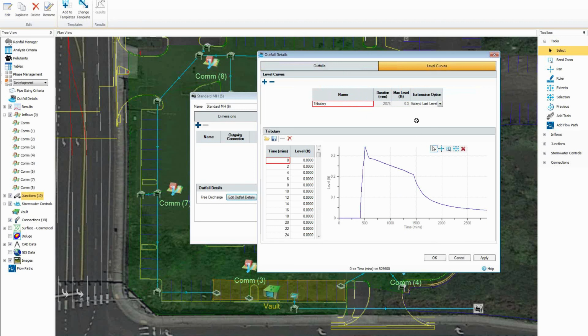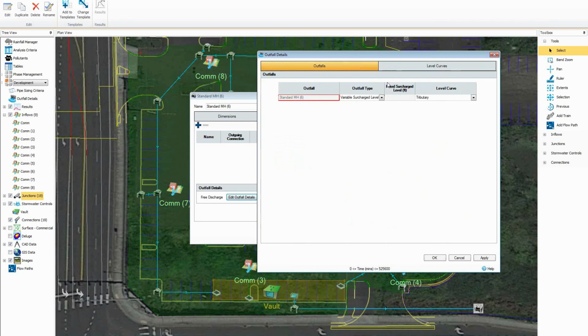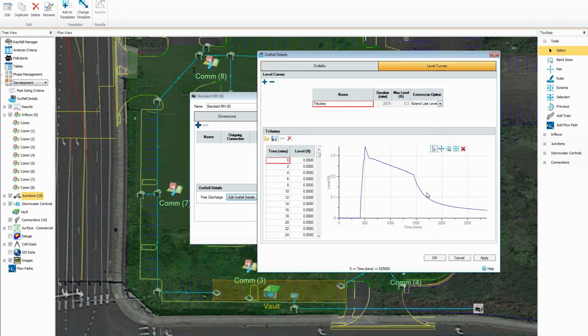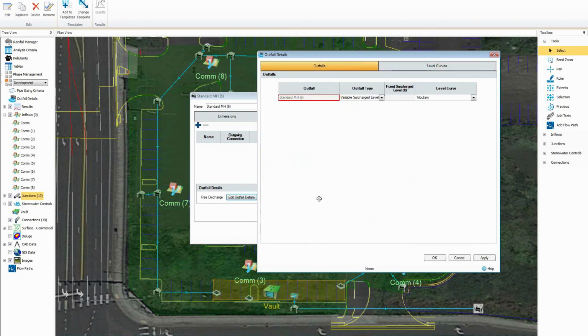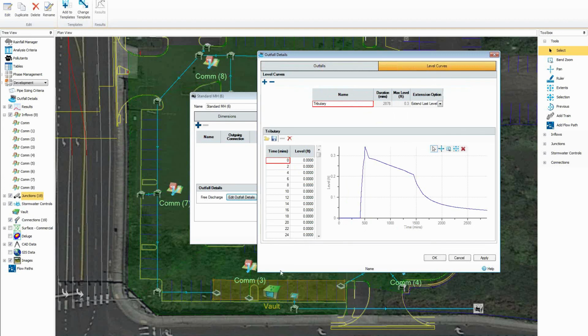And what's really useful here is that not only can we now specify a curve for an outfall, but we're going to be able to set up a curve for each outfall for each rainfall event. So really a matrix. In the real world, you'd probably have a different flooding condition at your 5-year versus 100-year. Maybe you have the same overriding hydrograph, but you can very easily specify a whole range of outfalls from your site, and for each rainfall event, apply a different variable curve.